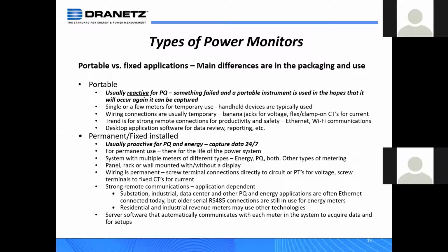So when you compare and contrast a permanent or fixed installation, as its name implies, these are permanently installed. The instrumentation or meters are there for the life of the facility. What that allows you to do is be proactive in your measurement, so you can see problems before they turn into failures. You can see proactively from an energy standpoint, look at your trends of demand, energy and utilization, and compare that to your utility bill, just to see if you're hitting some demand limits or power factor issues or whatever that may add to surcharges or additional charges for you.